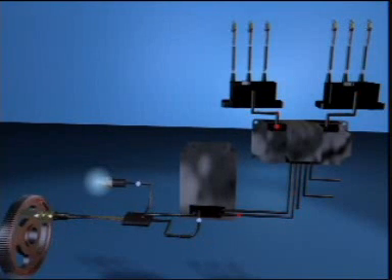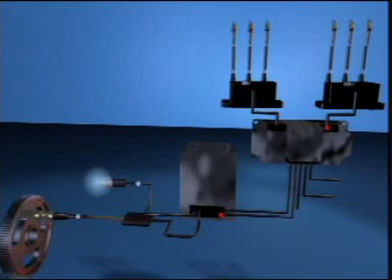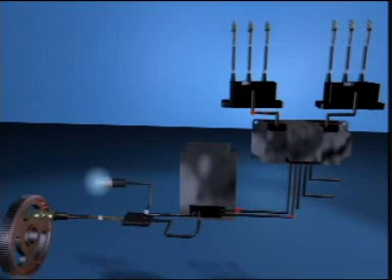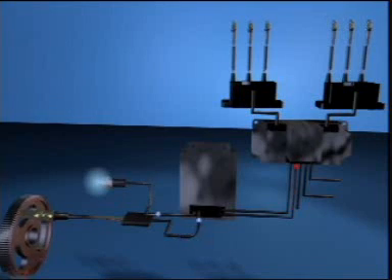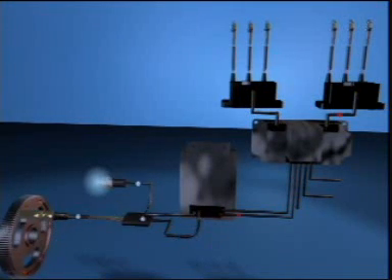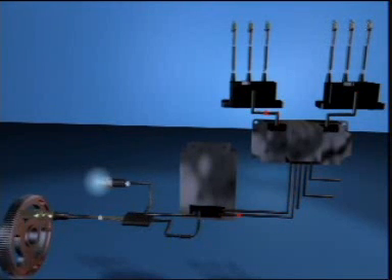The ICM sends out ignition signals to achieve the correct firing order of 153624. After receiving a spark reference signal from the ECM, the ICM fires the spark plug for cylinder number 1, then the next spark plug in the correct firing order each time it receives a spark timing signal. After firing all 6 plugs, the ECM sends another spark reference signal to start the sequence over.